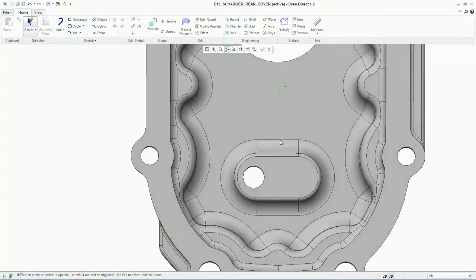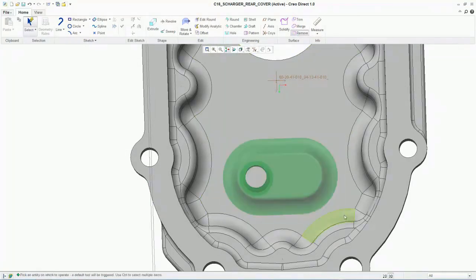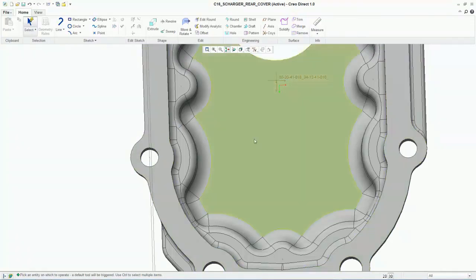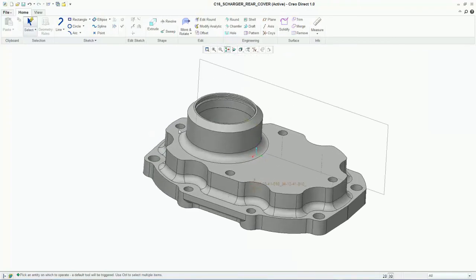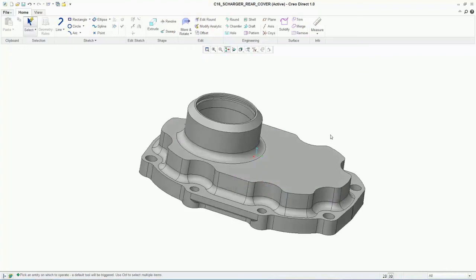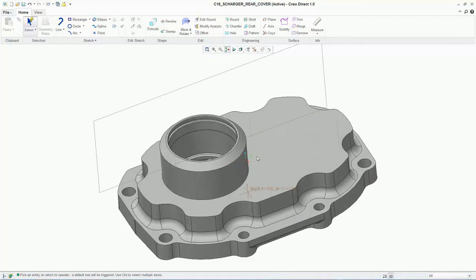The Remove tool in Creo Direct provides a quick, easy command that shows how simple it is to group select and remove unwanted features. The manipulation and removal of unwanted or unnecessary components is seamless using the Remove tool. The operation forces adjacent surfaces to converge, removing the barrier surface between them, essentially removing the object. We can use Control to select multiple entities, or use the selection dragger box to highlight the desired geometry. We can also remove rounds and holes with the click of a button.